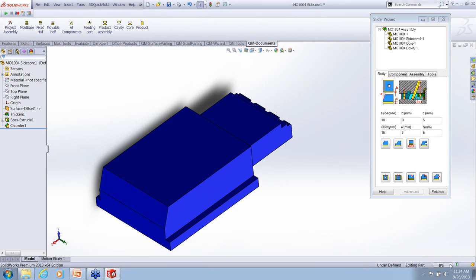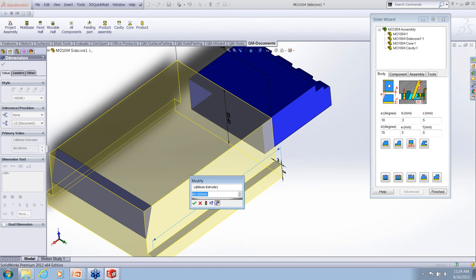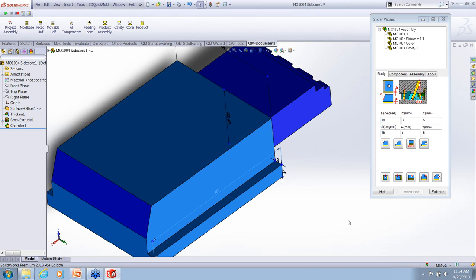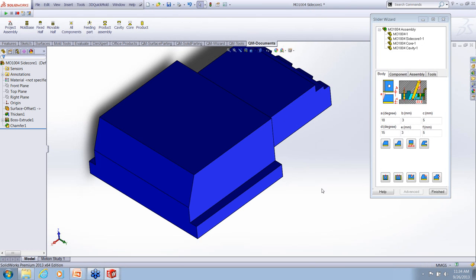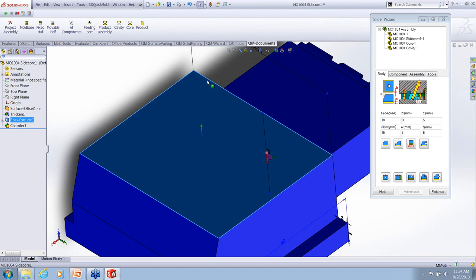If any changes are required, we can still modify. This is all with the dimensions on the screen. At the same time you can edit the dimensions. Let's have a look here. I'm just going to change from 60 mm to 40 mm, and immediately this is going to update the moment you rebuild it. Now I'm just going to create a finger cam hole on this.